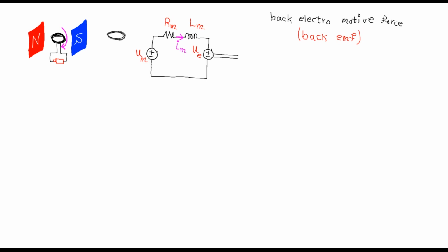The motor also has a shaft which is rotating with the angular velocity of omega m and generates a torque Tm. The shaft is also connected to a disc, or basically the load. We can also apply external torque to the disc represented by Td. This simple model has basically two parts, the electrical circuit and the mechanical part.